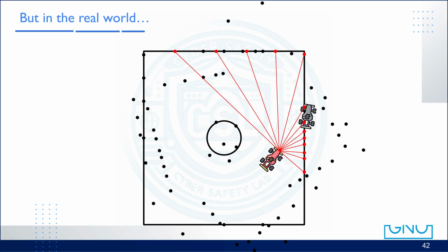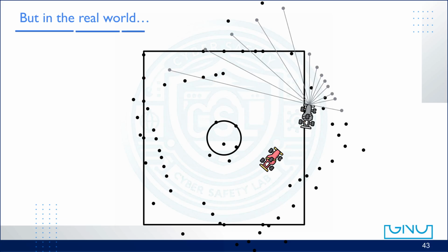If the robot keeps mapping while believing the wrong pose, all new points lose their meaning. The rectangular room we expect can no longer be reconstructed. Point clouds accumulate in incorrect regions, destroying the structure of the environment.